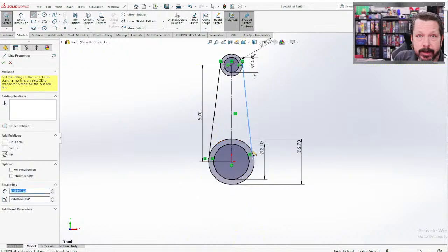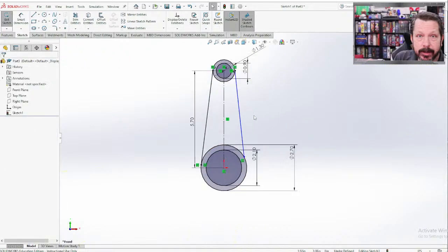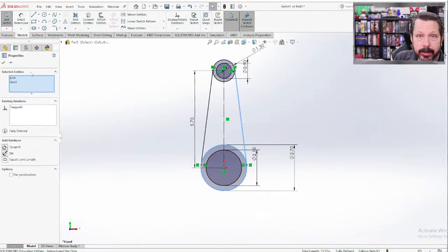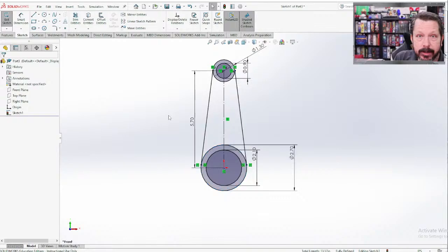That would have worked. We are going to mirror it in the simulation, but just to save some processing power. Because if you have any symmetry, like half bilateral symmetry or quarter symmetry or anything, then that will speed up any of these simulations that you have to do. Because basically the simulations are based on the number of elements, the finite elements, and there might be thousands of finite elements in there, and if I can half that number by having bilateral symmetry, then I should speed up my processing time because it doesn't have to process as many elements.